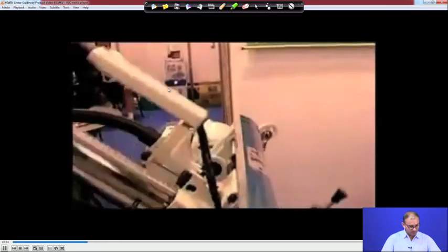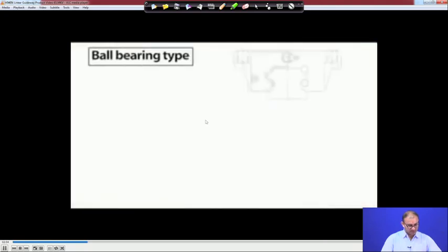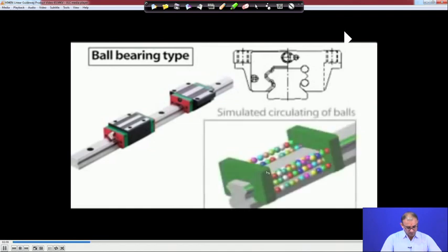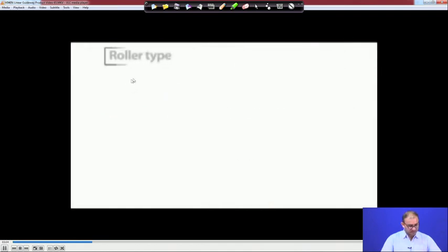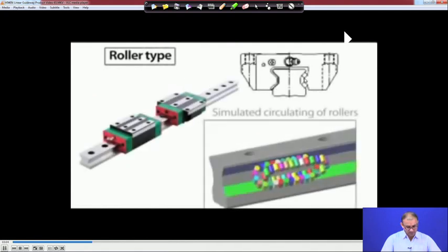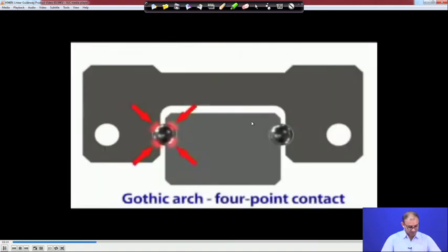So, this is the vertical motion, and if you transfer in another direction, then you can get different kinds of motion. This is used for the ball bearing. Now, if you are using a ball bearing, then this particular motion will be something like this, and the other thing is the roller bearing. Instead of balls, we are using a roller. So, you will get a line contact, and you may get more load carrying capacity in this case.